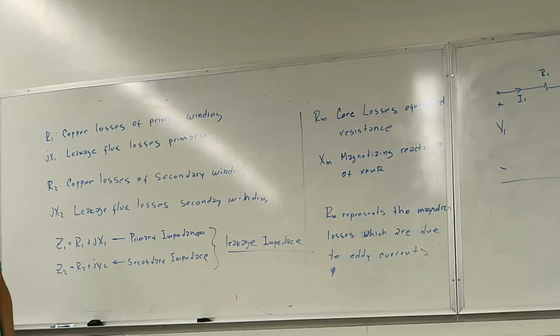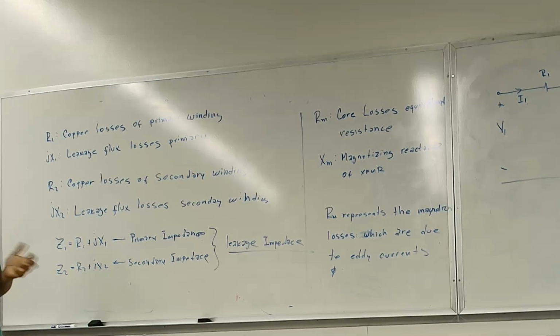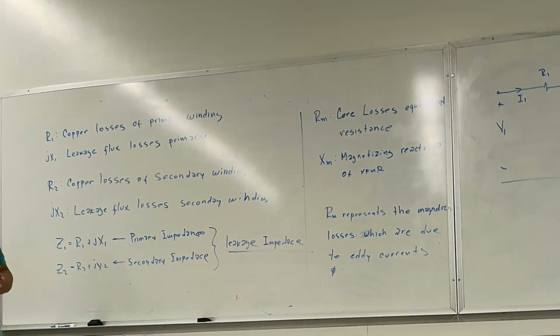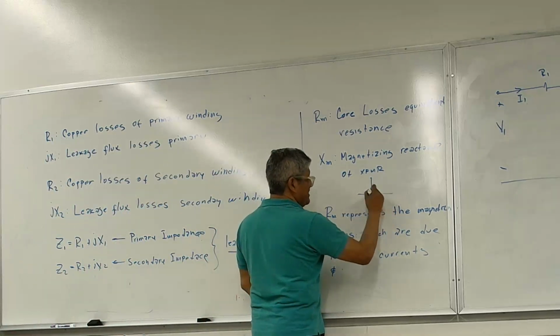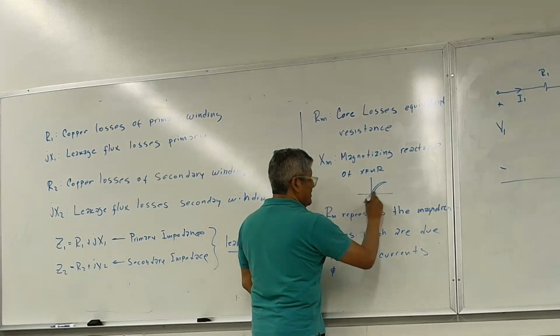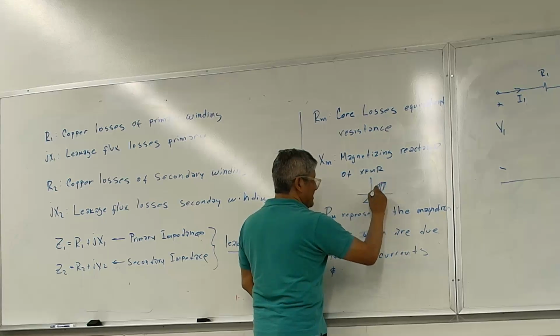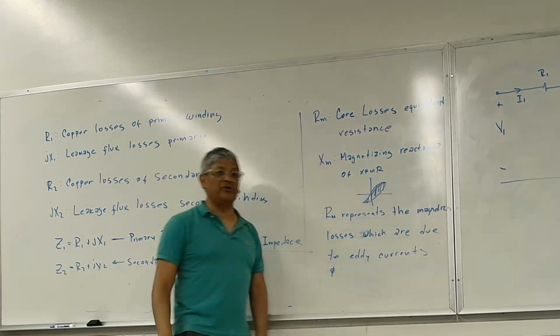How do we manage the hysteresis? By the material that we use. The better the quality of the material, the less your hysteresis losses. And remember, I think I mentioned this, if I didn't, I'm sorry, the area inside this curve is what we call those losses, right?